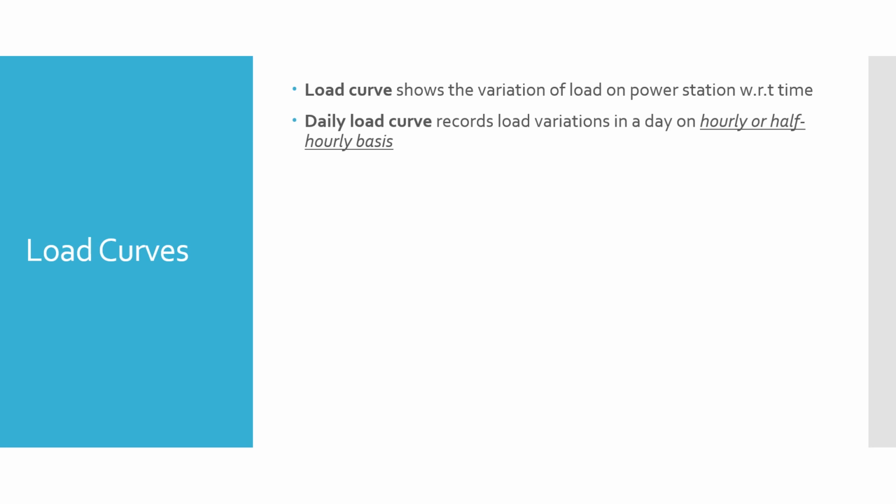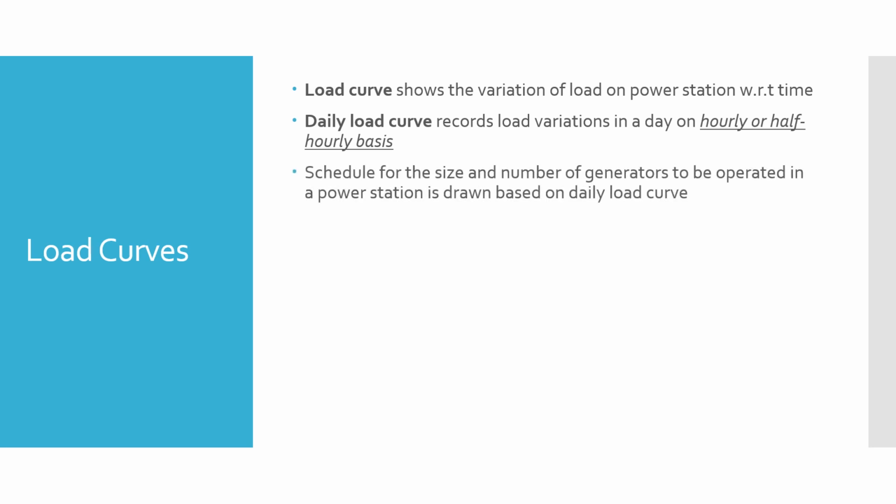Your time axis will have the number of hours in a day, and on top of each half hour, the value of average load which occurred during that time slot would be placed. This is a sort of sample and hold principle. You take the average of the loads which occur during a half hour time slot, and that average is represented as the overall average load of the designated time slot.